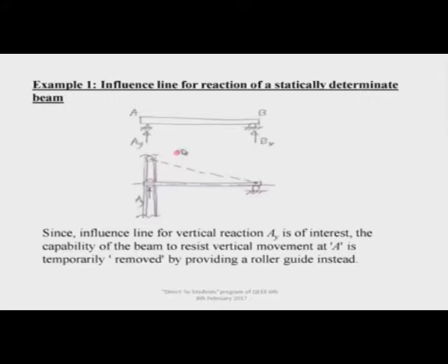In fact, if you draw, it will be a circular arc. We neglect that. We say that this is the new configuration. You have to accept this in the true sense when the deformations are very small. Suppose a few meters span of beam, how much does it deform in terms of millimeters? It's even a fraction of a millimeter sometimes.